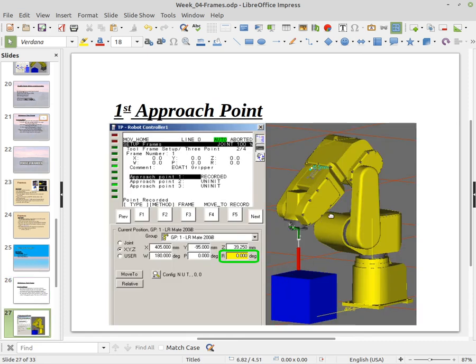All right, so here we have a robot, and this is in the course in the RoboGuide software, and I'm trying to teach a point in space. What I've found is that you want to have a sort of reference point to teach that point in space. So you see here, I've taught this first point perpendicular, coming straight down to my reference point. Now notice the reference point itself doesn't matter. The reference point could be anywhere in space. It doesn't matter where this reference point is.